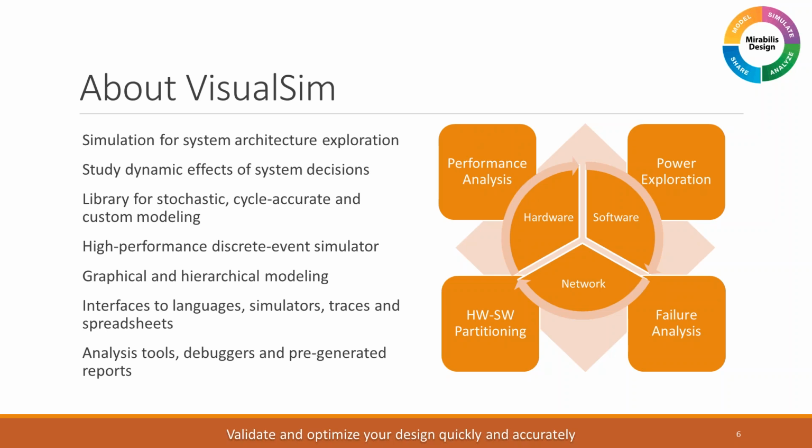When you look at performance, what you're really thinking about is timing analysis: what are my latencies, the amount of effective throughput, or quality of service I'm getting. Power is looking at your instant, peak, average, and cumulative power, either at a per-IP level or for the entire chip.